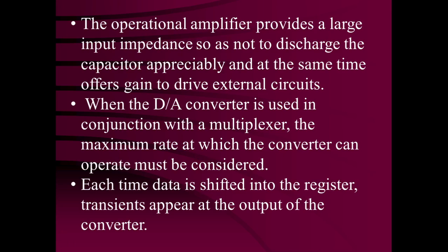Whatever the sampling rate is, how many times a sample has to be given, depends upon the capacitor being used. The capacitor is charging and discharging, and holding that information. So the capacitor should be charged very fast and discharged very slowly, and before it is discharged sufficiently, the next sample has to be available. That means a very large sampling rate is required.